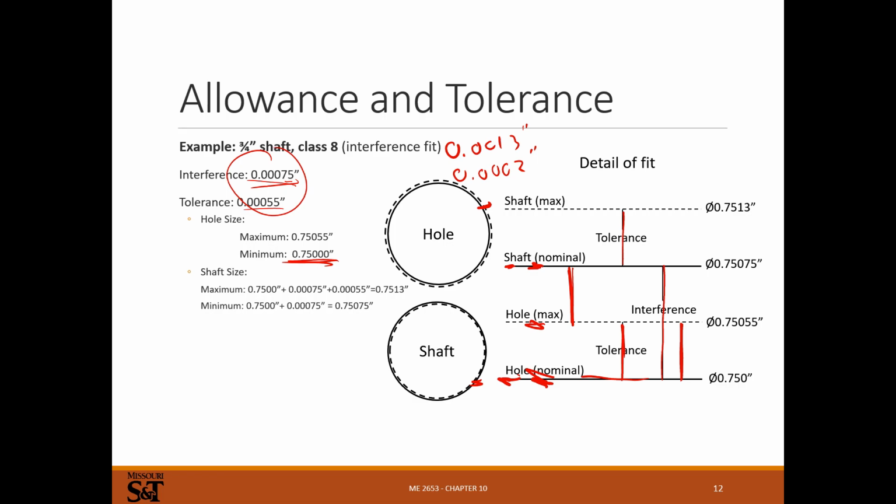Again, if you're doing mass production, it's all distribution. So you really want the distribution of this to be, I'm drawing terrible normal distributions here. There's a better normal distribution. Right, you want your mean somewhere in the middle here, and you want to make sure your process is tight enough to then get you within that tolerance window here.